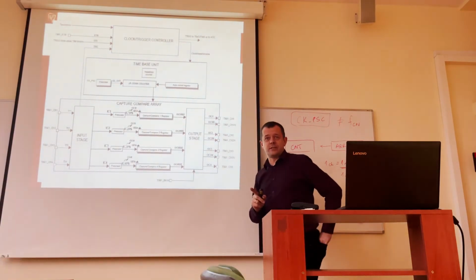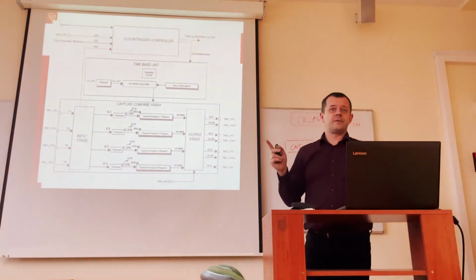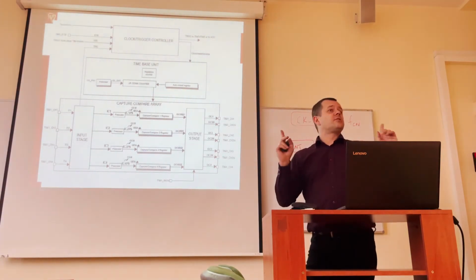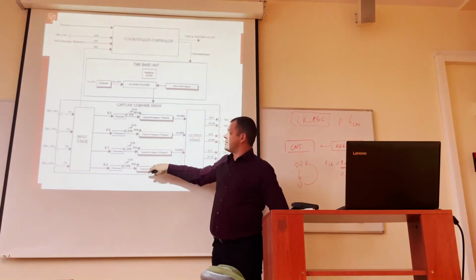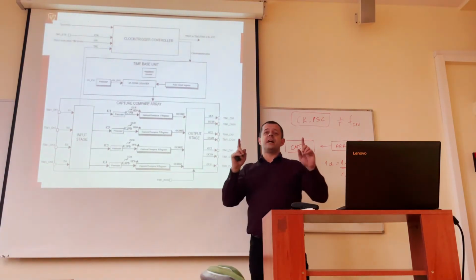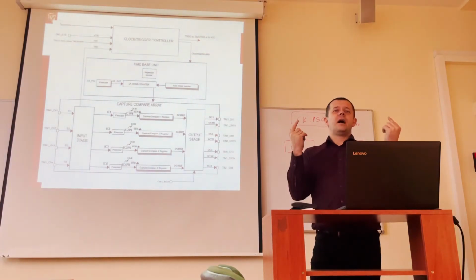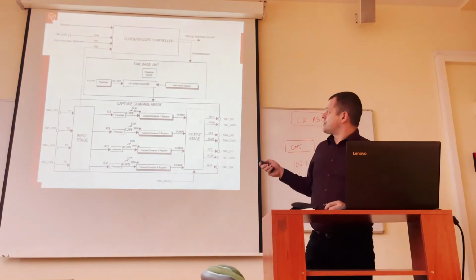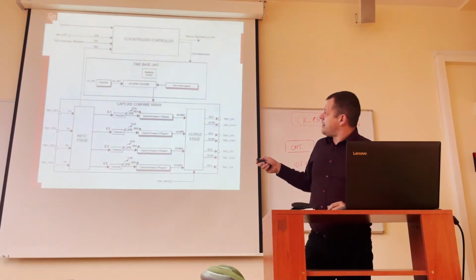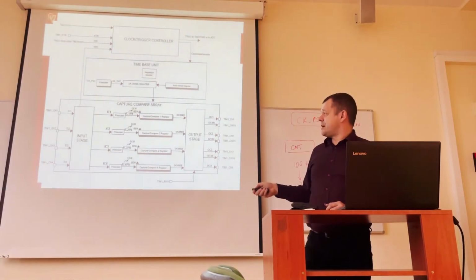That's one functionality. Another functionality is that we can measure the period between two occurrences of something. That's also possible using this input stage and these registers. In this register we get the difference, not how many times something happened, but how often it happened. So when was the last one? Actually, we've got a snapshot of this value, because that's how it works.